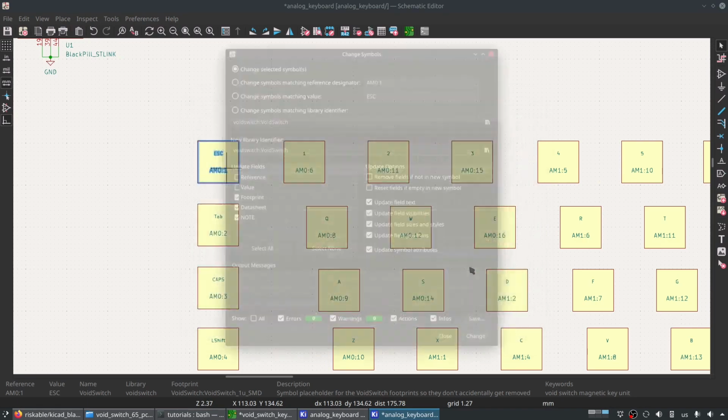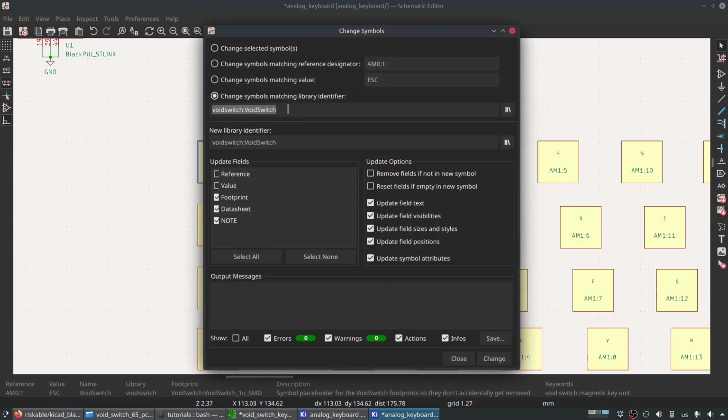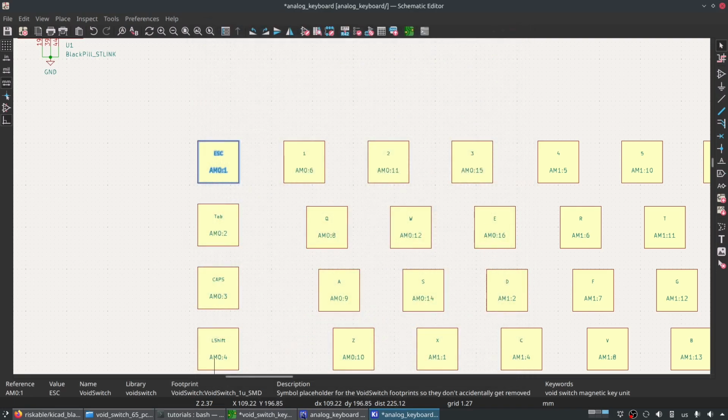The reason why change symbol isn't working is because this symbol doesn't actually exist. It can't find it. It's not doing a text-based search. It's actually looking for anything that actually has the symbol, which it can't find, right? So since it can't find it, it can't change it to something else, right? So what I'm going to do is, this is what you do.